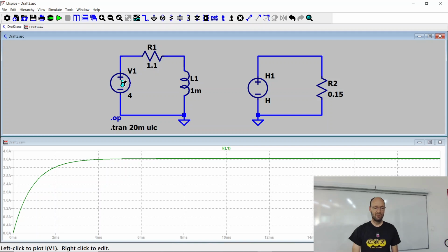So we can just use this voltage source as a sensor, and we will take the current through this voltage source and then put it into this source here. And as discussed, the current here is pointing in the wrong direction, so then our trans resistance, the K factor, needs to be negative at the end.